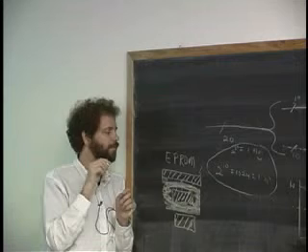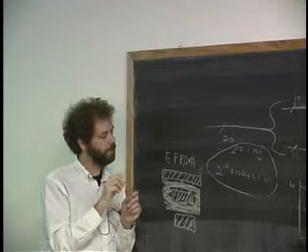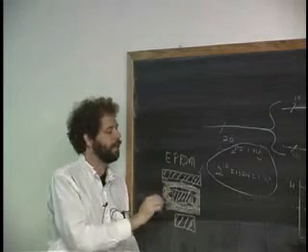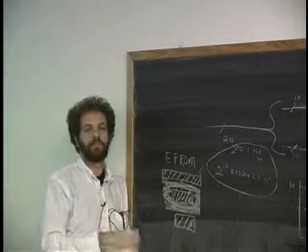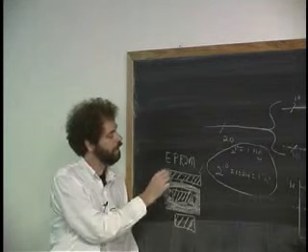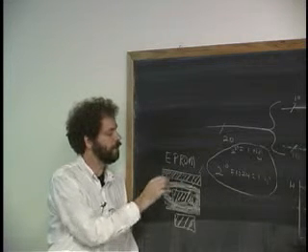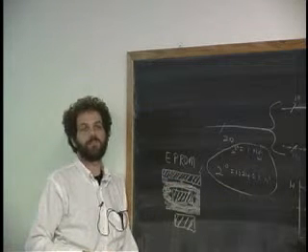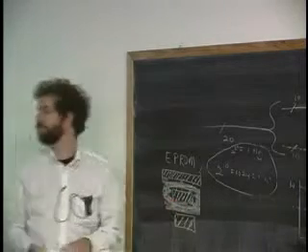If you shine a really strong ultraviolet light of a certain wavelength in there, certain wavelengths work better than others, depending on how the glass is made, it'll allow all the charge to leak off, and you'll basically clear the ROM. And then you can program it by setting certain of these plates to a high voltage, and it'll allow the charge to sneak on to certain ones. And that's how it's done. Okay, so if you ever see these chips being made, you'll actually know how the thing works. And you'll think about bathtubs, right?